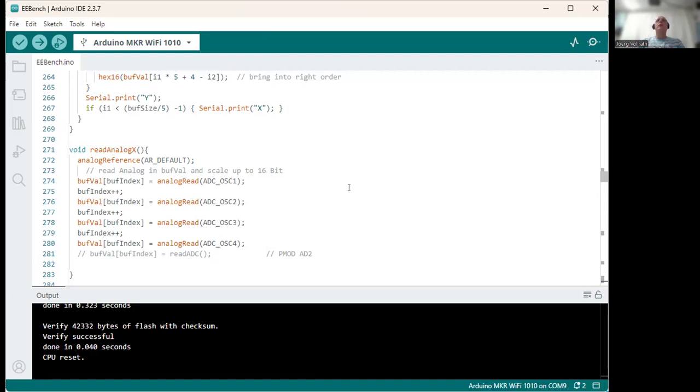This serial interface will also be used by the server to communicate with the Arduino and transfer data. So you have to be careful that your serial interface via the USB is not busy with the Arduino or with the Node.js. Every time after you are doing something with the Arduino, you have to restart your Node.js server.